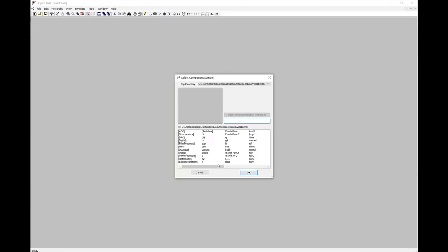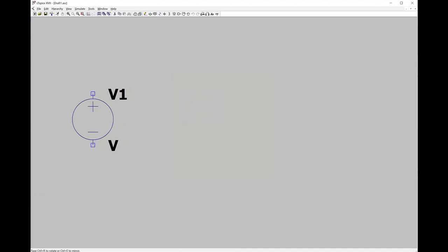So at first, we need to put down our voltage source. This component that looks like an AND gate has all of our possible voltage sources, all of our possible components in it. We can move over to our voltage source and place that. Hit the escape button to get out of place mode. We need a resistor. You can find that under components too, but people use resistors so often that there's a built-in resistor symbol up here. You can hit Control R to rotate these resistors around. Escape gets out of that mode. We'll use a capacitor next. Escape. And you always need at least one ground. So here's our ground.